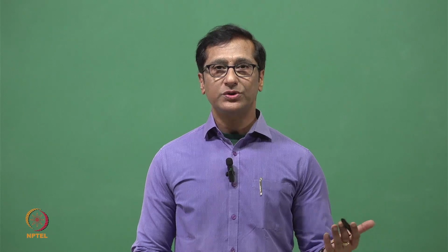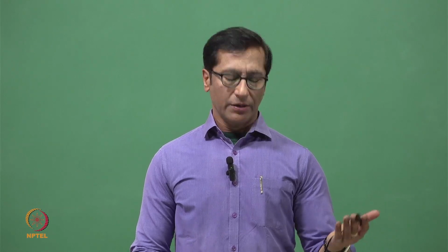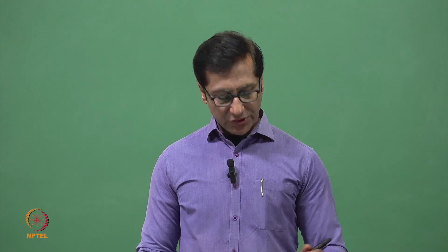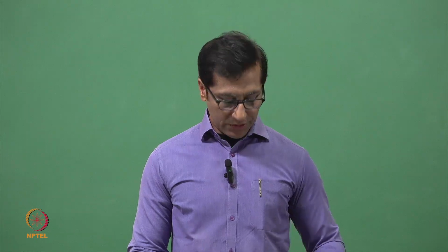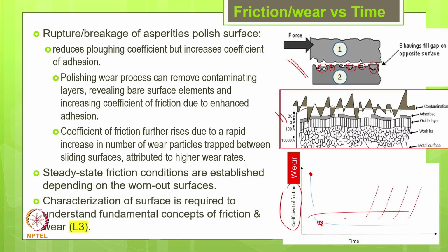Now these debris are not playing much role, and the surfaces are already smooth, not perfectly, but better than earlier. So in this situation the coefficient of friction will drop down. Initially it comes down like this, and it will remain there for some time. Depending on the circumstances, the debris initially filling the grooves may get tilted or may come out. Quite possibly the friction will again increase.